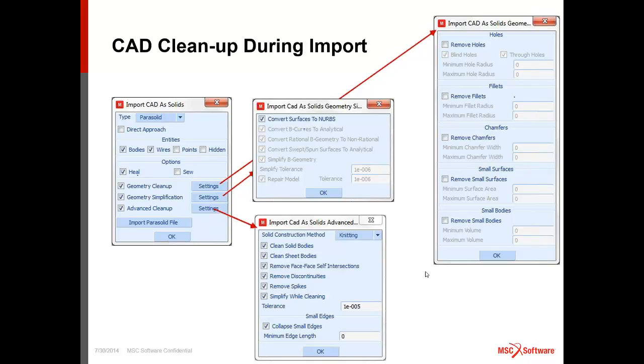We will also see that there's another way of defeaturing the geometry after you've already brought it in, and that gives you a little bit more control. And then there's a set of some advanced features, which is really trying to get rid of little holes in the geometry. The most important one is this one here, which is known as healing and sewing. And we'll see an example where doing healing and sewing was necessary to clean up some really bad geometry.